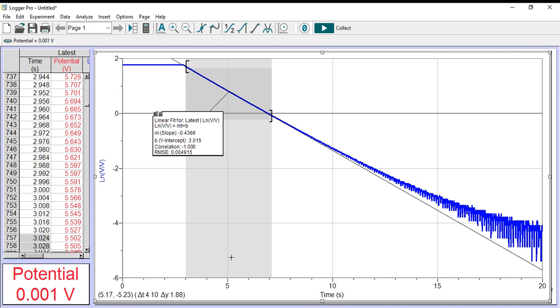The final thing that we need to do in step 4 of this experiment is actually try to calculate the capacitance of the capacitor. Now, the instructions tell you to go and get a data logger to record the resistance of the resistor. I've done this for you, and the resistance of the particular resistor I was using here was 998 ohms. So you can record that value again in part of step 4, and using that you should now be able to calculate the true value of the capacitance. This almost certainly will be quite different from the declared value of 2000 microfarads.